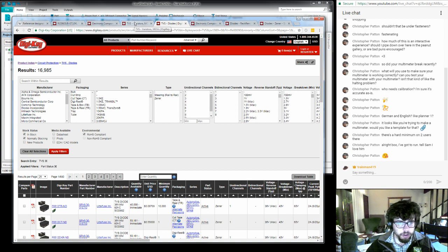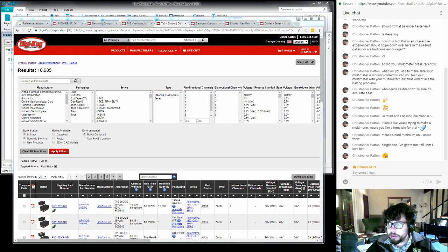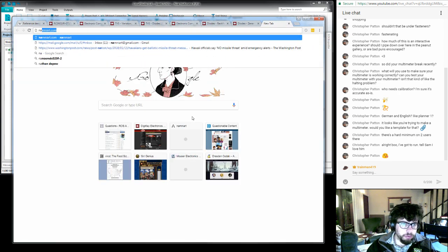It usually turns on at some high voltage, and then once it's at that voltage, it will conduct rather substantially to bring the overall system voltage down and prevent that voltage from showing up on the input to whatever other device you happen to have connected. In this case, I'm looking for a TVS diode for my input.